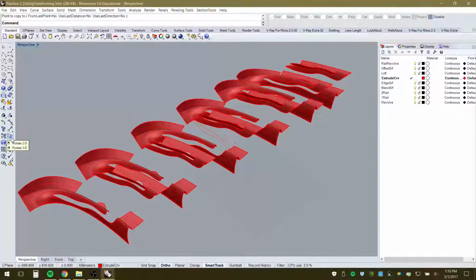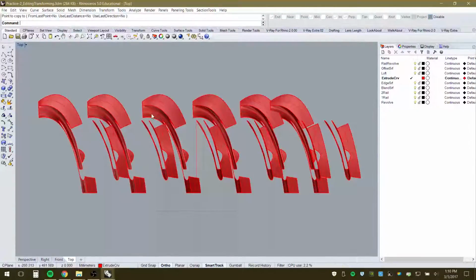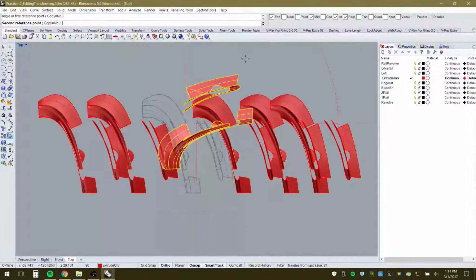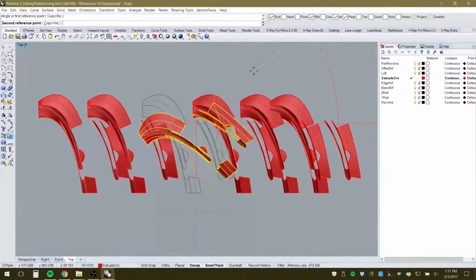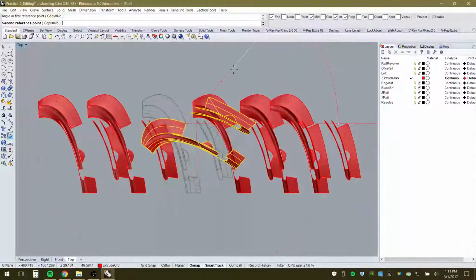Let's see, rotate. Rotate is pretty important. So again, there's a left click and a right click option for this. If I left click, I'm going to go into an ortho view because it's assuming orthographic orientation with this 2D rotate. So there's 2D and 3D. Let's take this guy and right click. It's going to ask me for a point of origin. So that could be a particular point if you wanted to. And right now, because I have ortho selected, it's 90 degrees, but if I want it to be something else, I can hold my shift key down or just untoggle ortho and that would get rid of that, but I could sort of rotate it that way.